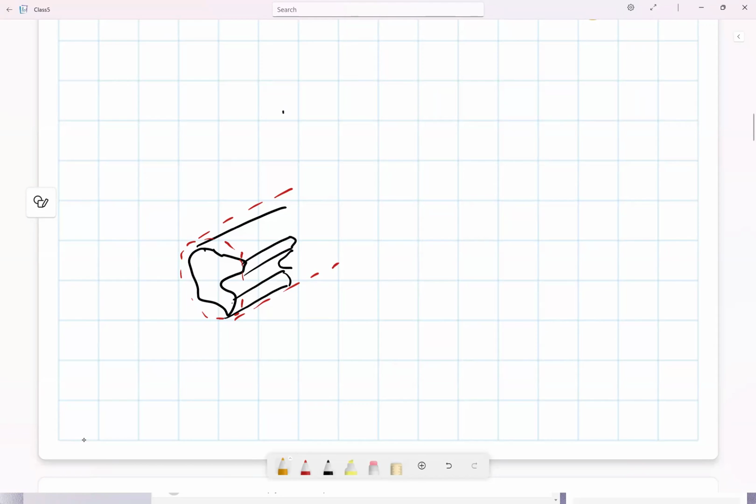So if you're going to solve a problem with a conductor with that shape here, I would say first solve the problem of a cylinder, validate it, and if your finite elements give you the same as your analytical solution, then I will believe it. Then you modify it, and I will believe that is correct.